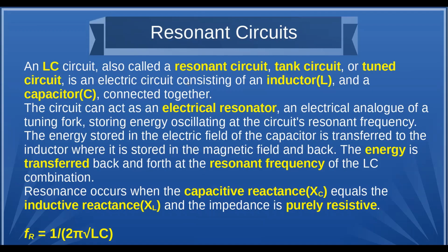In order to keep it resonant, like to create an oscillator, you need to provide enough feedback to compensate for the loss to keep it oscillating. Because in the real world, there will be some resistance in both the capacitor and inductor, so you'll lose some of the energy as heat. So it's resonant when both the capacitive reactance and the inductive reactance are equal and opposite, so they cancel one another.